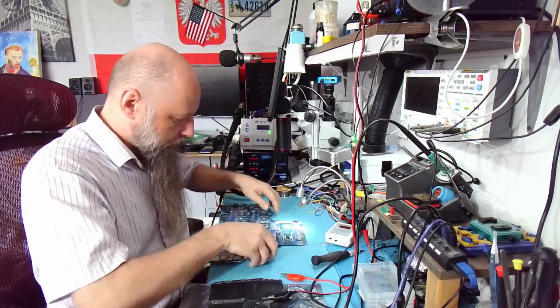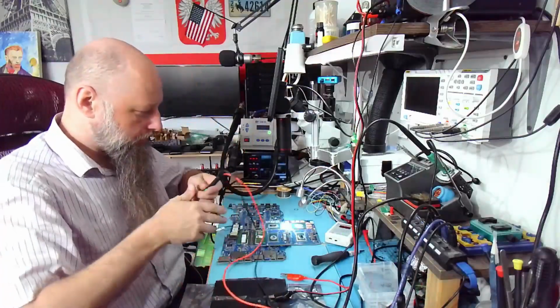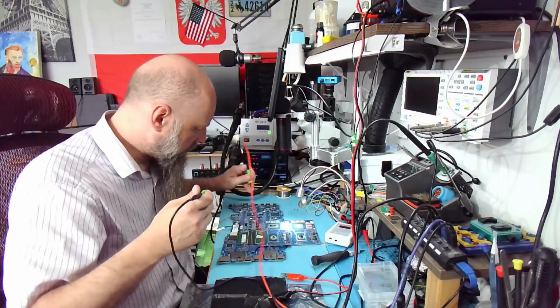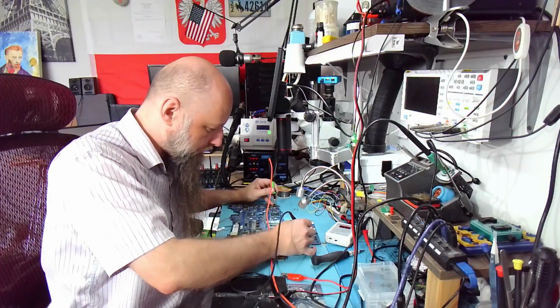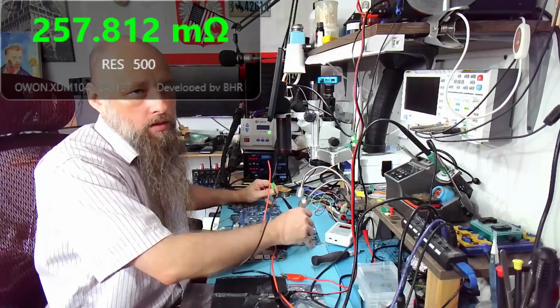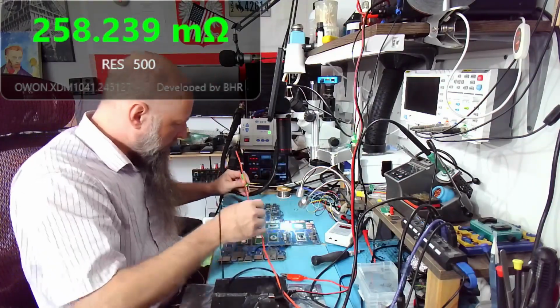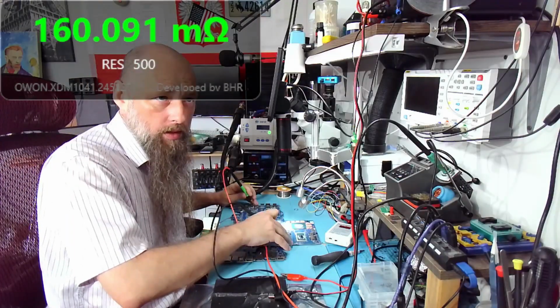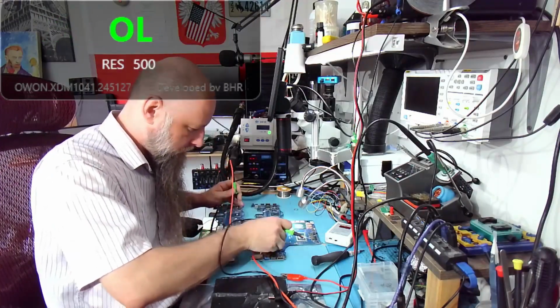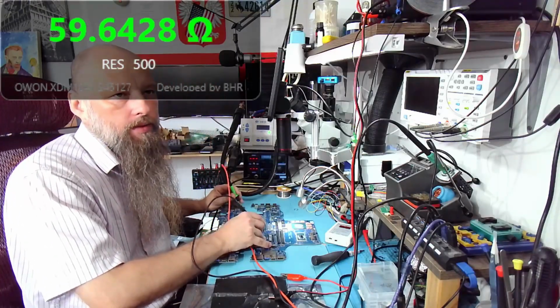Let's just confirm. So now that we have both boards out here, let's just confirm that the CPU is indeed faulty. All right, so this is the replacement. No, this is the original, and we have pretty much nothing on vCore. 250 milliamps, so around 200 milliamps, and on the working board we have that is unexpected. I thought I confirmed that. Oh right, yeah, I didn't confirm.